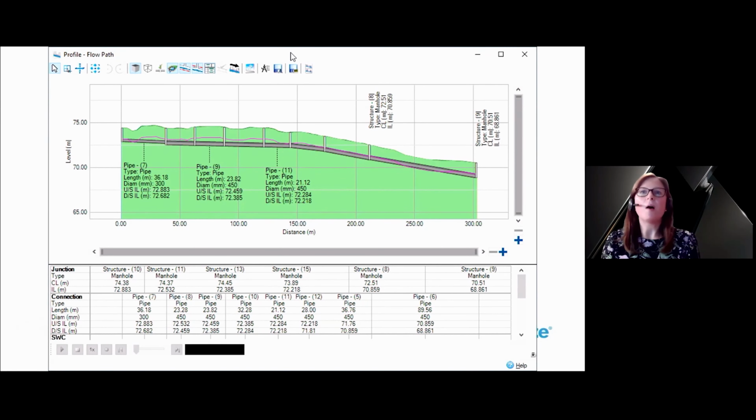Then with a pipe network, we would use the network design tools to size the pipes for accepted flow capacity and to meet additional design criteria such as slope requirements, minimum cover level, backdrops, velocities, and outfall requirements. We could then also add storage and green infrastructure and complete the hydraulic analysis to check against performance criteria.